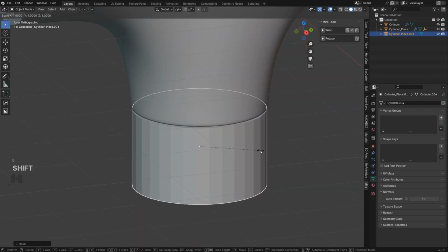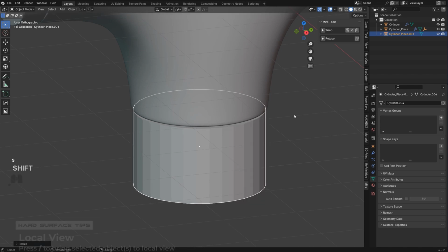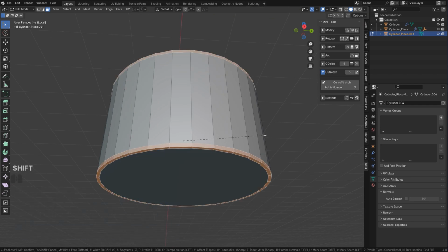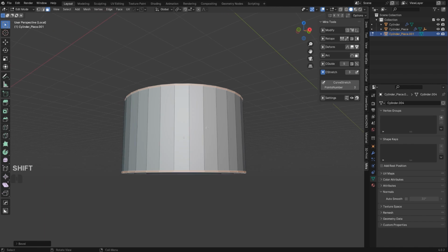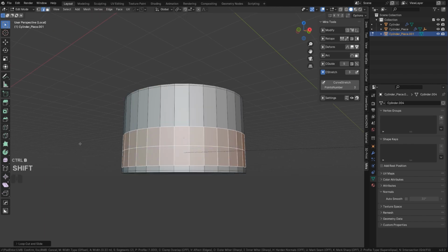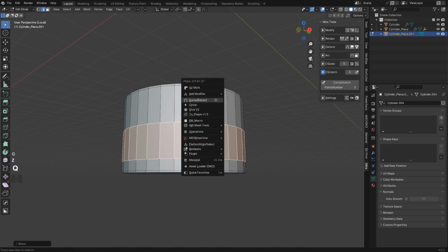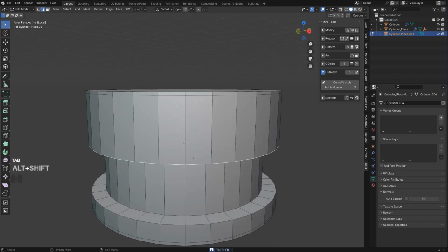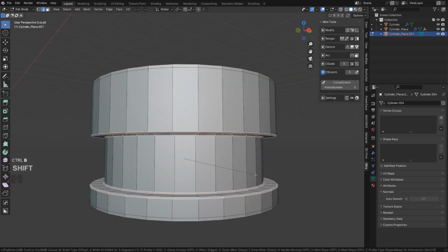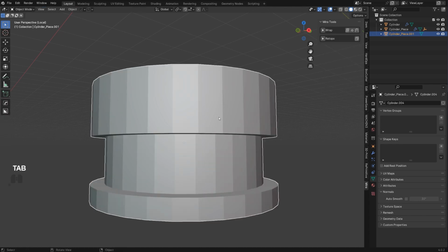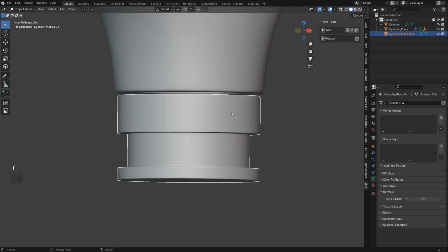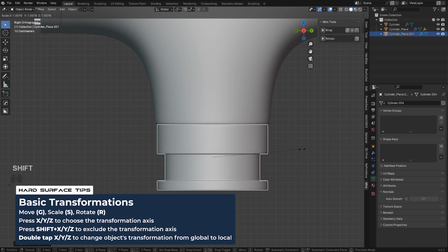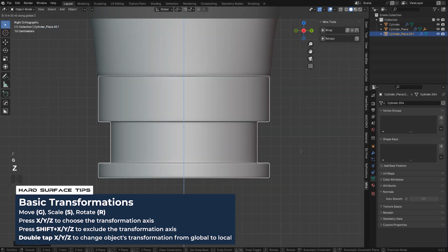Just drop it down a little bit, and let's just secure it from both sides like this, and we're going to introduce kind of a groove in here with Alt Q and macro. Boom, and then select all the edges here, right, and just bevel them. Okay, Control 2 and it's smooth and peachy. Then we need to connect them, so GZ, move it up and just slightly make it larger, so it kind of